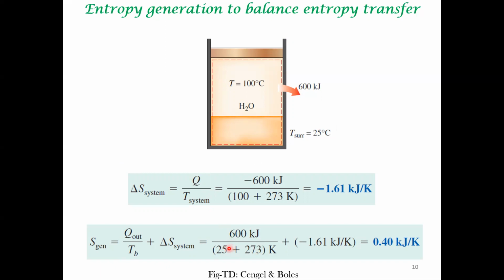And then when you add up this positive quantity with the negative quantity, there is a difference. Okay, so it's not zero. So some new entropy is generated. Crucially, the difference between the temperature of the system and the environment, this temperature differential, is the prime, central reason for entropy generation.